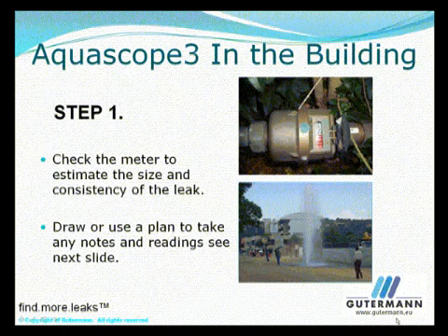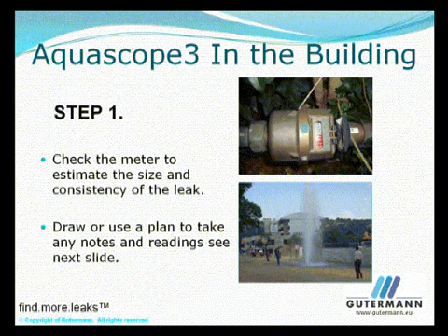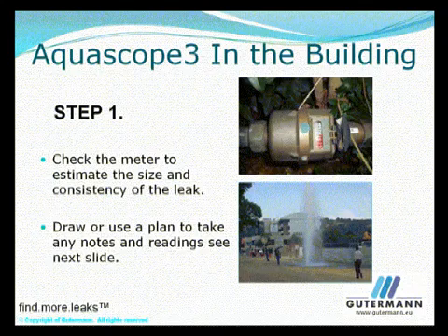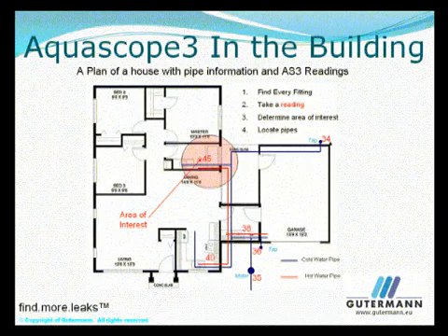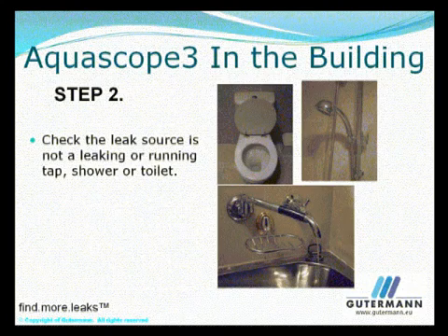In the building, check the meter to confirm there is a leak and estimate the size. Draw a sketch of the building, record your results and determine your area of interest. Check the leak source is not a faulty tap or leaking toilet.